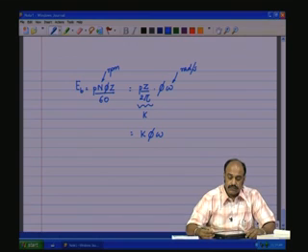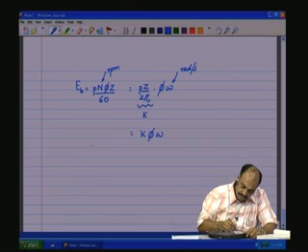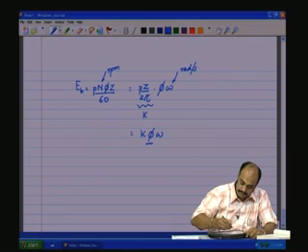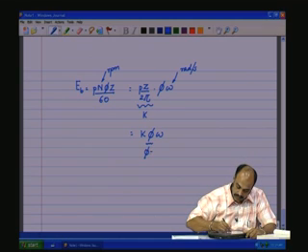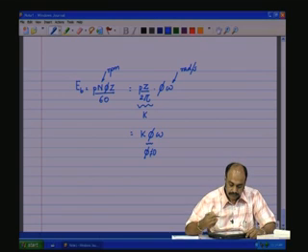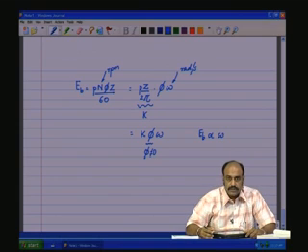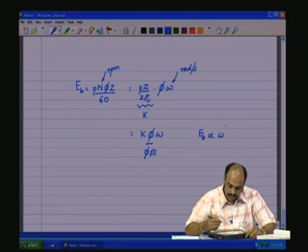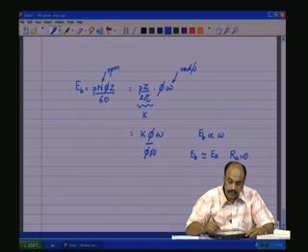Now, let us say in the case of the shunt motor, this is given by the applied voltage, which is connected across the terminals, and therefore, phi is not 0, and Eb is proportional to omega. When omega is equal to 0, the induced EMF is 0. If the flux is brought to 0, what happens? Now, Eb is approximately equal to Ea, and let us say for the moment for the discussion Ra is equal to 0, then